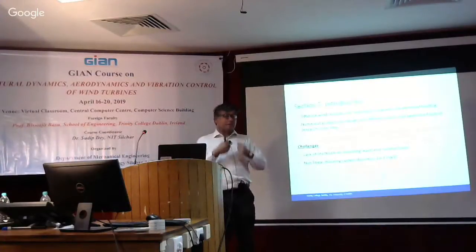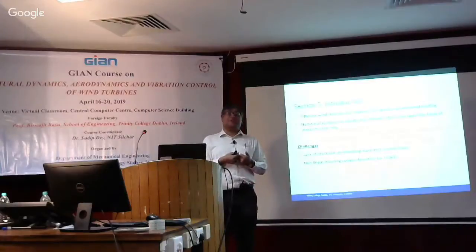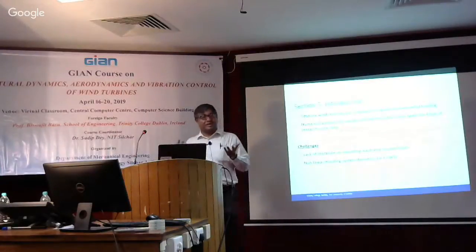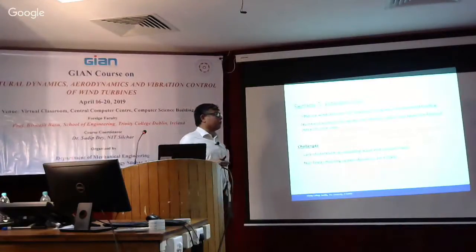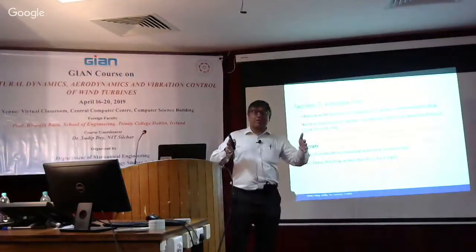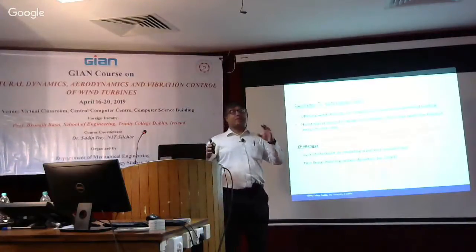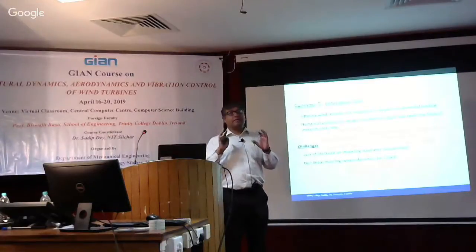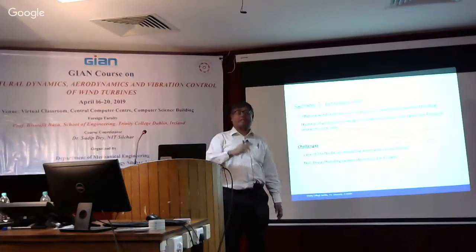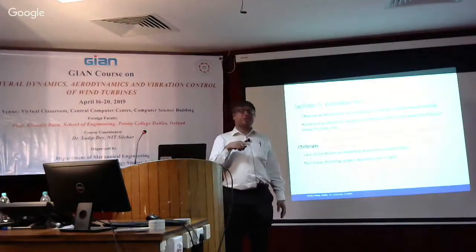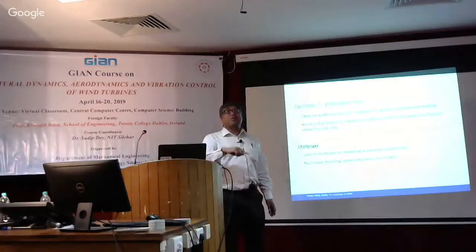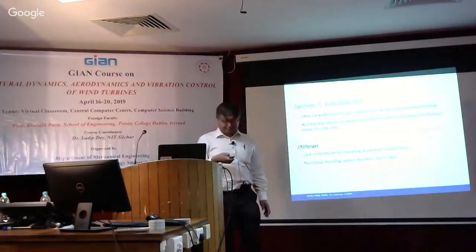It is particularly difficult for offshore wind turbines. Also, because the platform is not fixed, you have degrees of freedom at the platform, which induce various complex motions of the blade and power, and therefore you need the pitch and generator controllers to be designed to take into account all these phenomena.